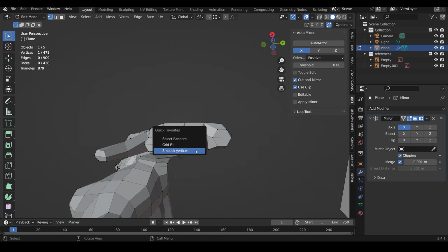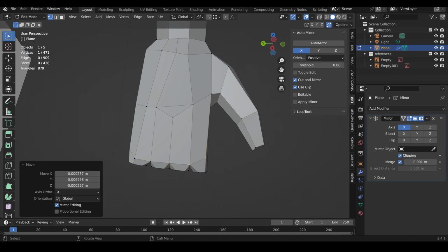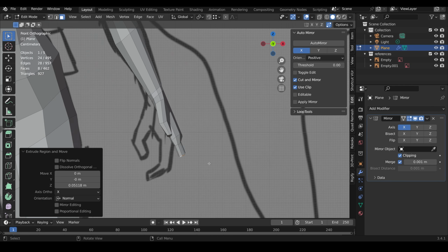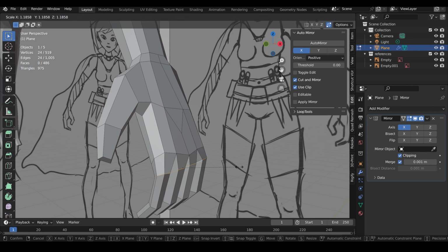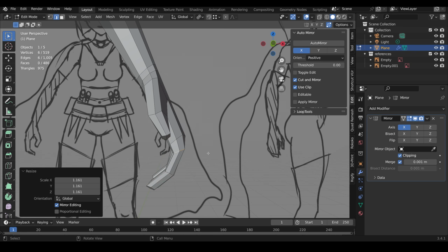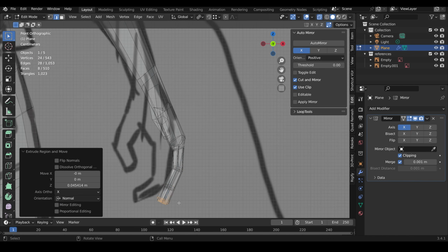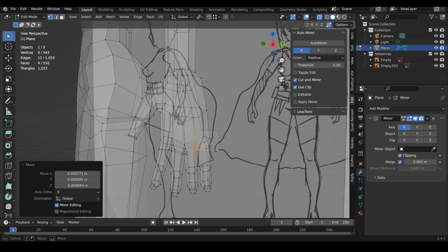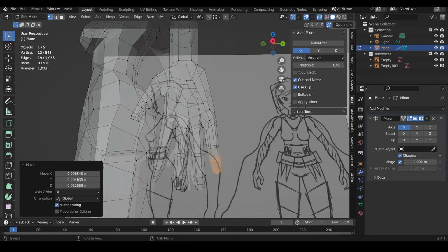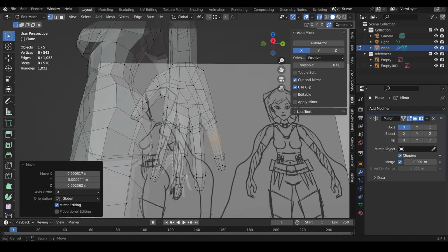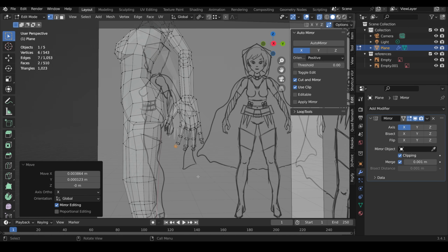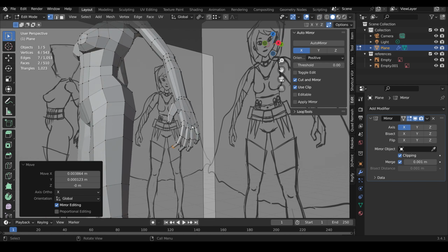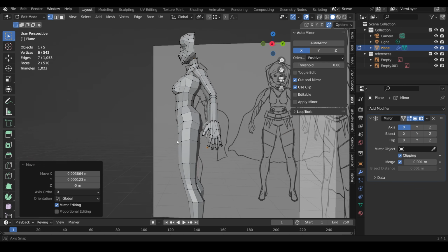There's a to sphere option, or you can use the loop tools add-on, and to circle is the option on there as well. And you can make them rounded. Make sure you make them rounded before you extrude. It's quite awkward afterwards. After that, it's about pulling them into position, and do make sure that you've got that curve to the fingers. You've got your little finger that sort of sits back slightly in the hand. And if you look at your hand and relax, you can see it's got a sort of curve to it. So it's good to set them up like that. And there we have our hand.